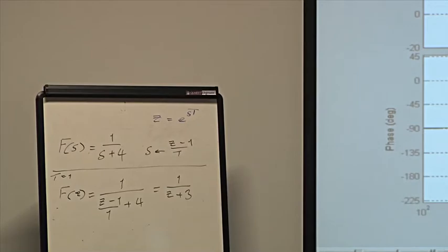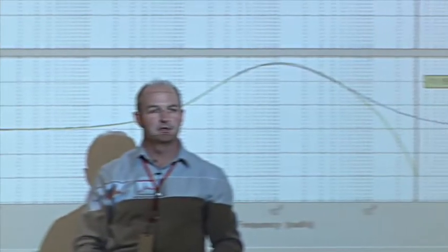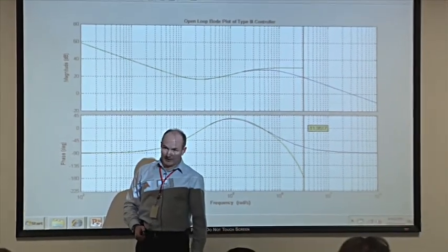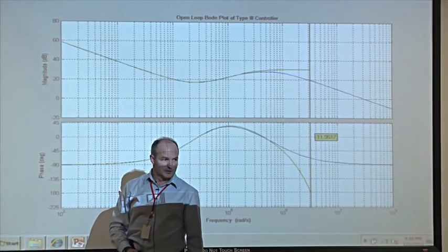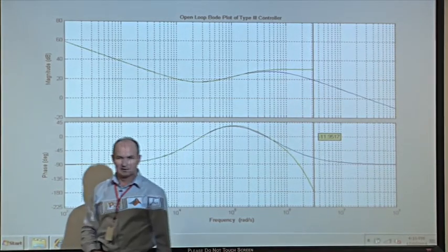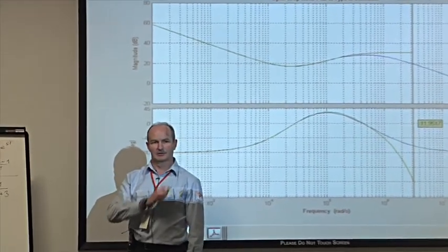That is the z transform of that transfer function for a sample period of 1 Hertz. Now there's a problem with that. Can anybody see what the problem is? Somebody saw it, I know you did. I didn't catch all the words. If the word unstable was on anybody's lips, that's absolutely right.